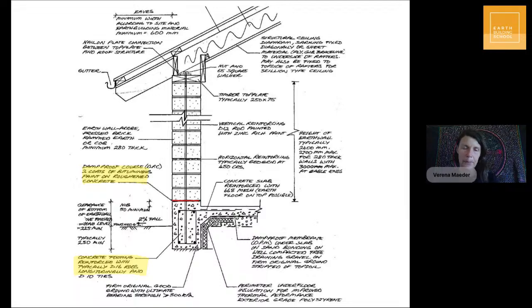Very important is that when you're having a foundation, often you're using concrete, so steel reinforced concrete for that, especially in Aotearoa, New Zealand, where we have earthquakes. This concrete foundation is pretty much the only thing you can do, unless you work with an engineer and they find a safe solution for a really strong foundation that uses other materials. In other countries, you can consider things like rubble trench or stone foundations. So inviting you into looking at options there.